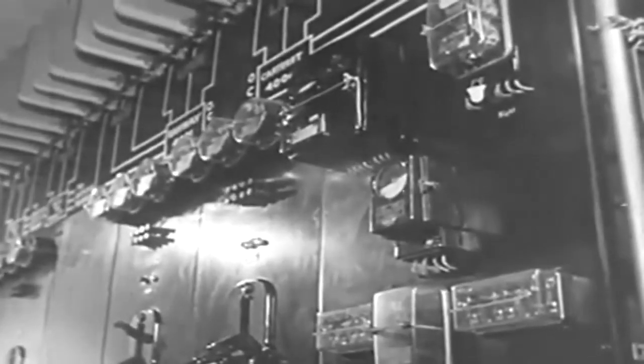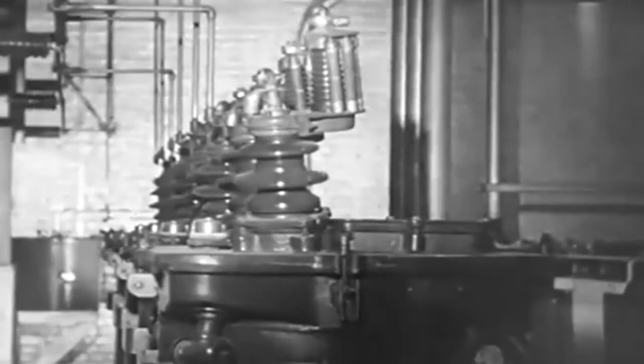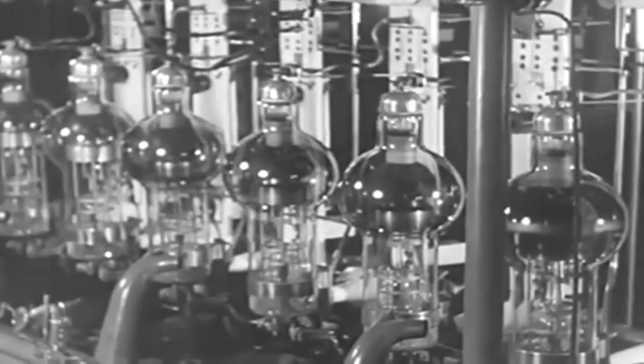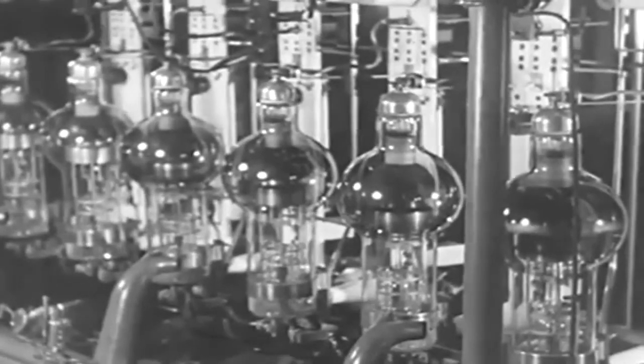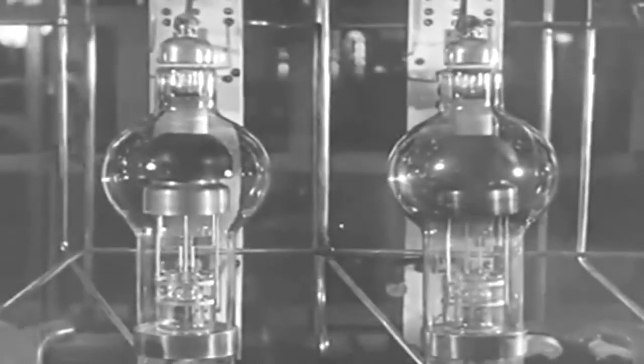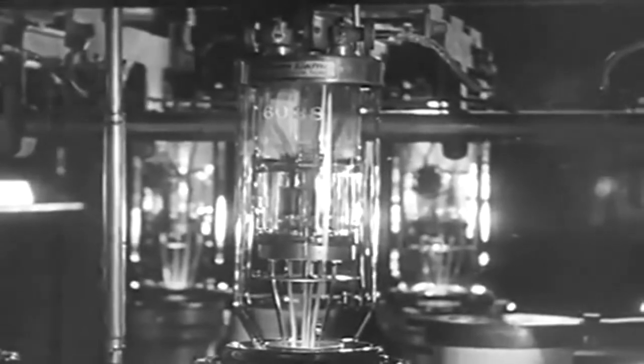This is the primary power source of the transmission station, where current comes in at a high voltage. These transformers convert the incoming current to a high voltage necessary to secure dependable long-range sending. These vacuum tube rectifiers convert this alternating current into a direct current. Power tubes operating on this high voltage are used to amplify the modulated waves received from the modulator tube. Several power tubes are used when great sending power is desired.